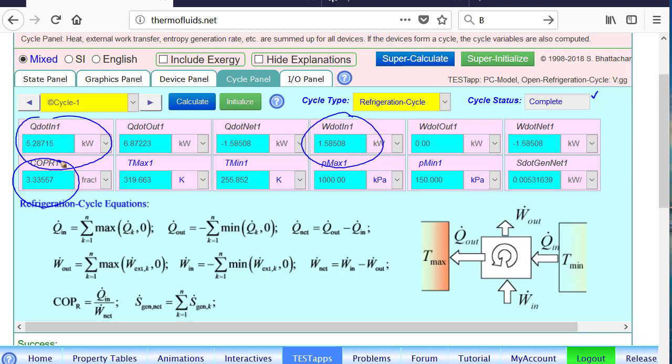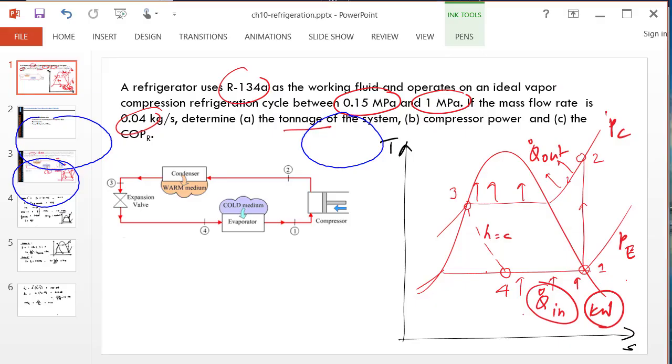So what will happen, suppose, if we increase the condenser temperature? You know from the Carnot analysis that COP should go down if the difference between the cold and hot temperature increases. So if we raise the condenser pressure, then the temperature at which condensation occurs will increase. Therefore, the difference between TC and TH is being increased.